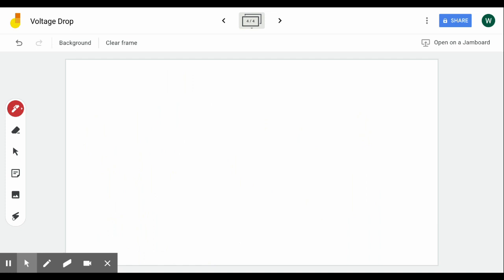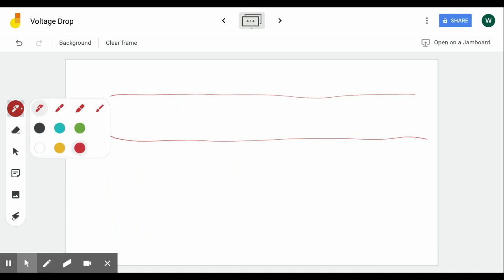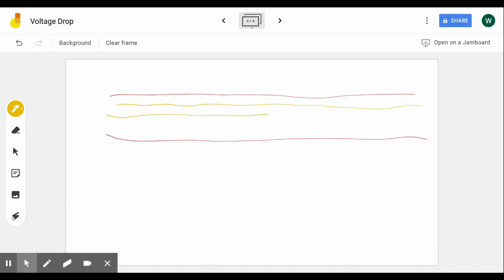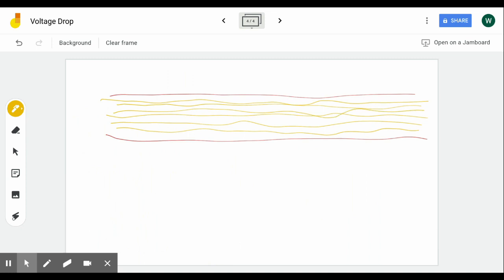So let's take something like a battery cable. If you were to cut apart a typical healthy battery cable, what you would see is an insulator that runs around the outside of that cable. And inside that cable, you have these strands of wire running through it. I'm drawing this, obviously there are thousands of them, I'm just drawing a few so you get the idea. We have these strands of copper that are all working together in order to carry the current through the wire. Well, this would be a healthy wire.